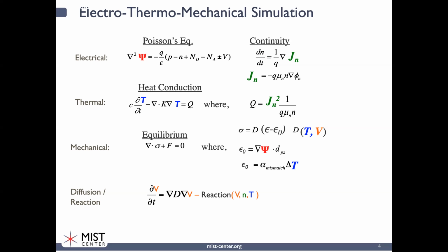We are coupled into a mechanical simulator, so we can solve for elastic problems and compute the elastic strain that's present. And I'll talk a little bit about that when we go and talk about the Hall sensor work as well, because we're interested in how mechanical stress changes the Hall sensors. And then finally, we can also do diffusion and reaction equations. So for example, we've coupled vacancy and interstitial motion in capture at interfaces as part of our work on degradation and looking at how devices fail.